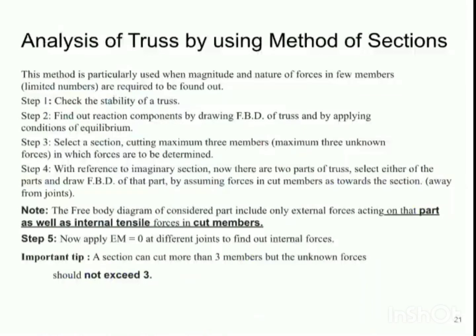Now let us move to the next slide, that is analysis of truss by using method of sections. This is a method which is quite easier, and it reduces the time required for analyzing the truss. Now this method is mostly used when we are required to find out the member forces of few members.